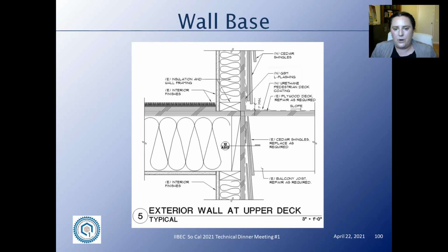And same thing with wall-based flashings. A lot of times these wall-based flashings are sheet metal L angles, and we can have a weak point right where the sheet metal L angle transitions to the plywood. We can also have a weak point if the wall waterproofing is not adequate. I have seen locations where this wall-based flashing is completely deteriorated because of water from above, and so now we have a very vulnerable spot right at this transition.